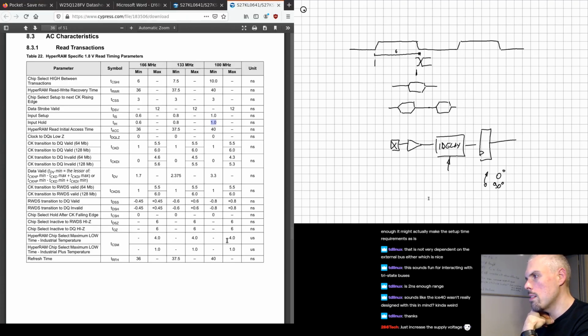These are the worst case timings, so most of the time the capture window is going to be larger than this, and you have more margin than you think. Of course, my sample size is relatively small, but I did always manage to find a capture window with a very wide margin of values that works.